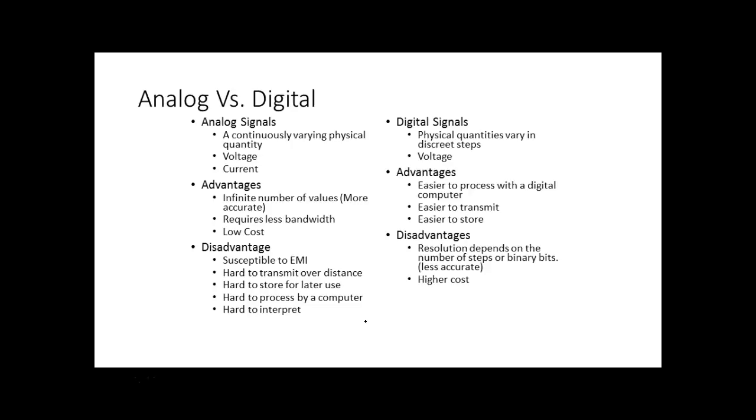Yeah, but we got to represent it with something. So if I'm going to bring it into a computer, that computer's got to represent that digital information with something electrical, right? You understand? And what's the most predominant method of representing ones and zeros? Voltage, yeah. We either have a voltage there or we don't have a voltage there. So a certain voltage would be considered a digital 1, and then we usually use 0 to represent digital 0.